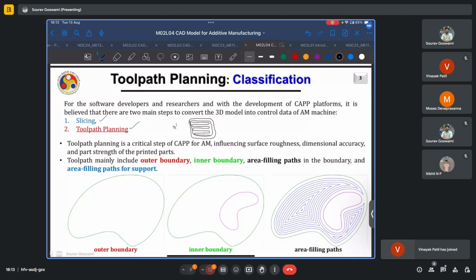And if this is for the nth layer, in the n plus 1th layer, based on the type of variation which you have, if you give any interlayer rotation or not, you will again have something similar. In a sense, it will be 1 or 2 perimeter passes. And then the infill, say if you have an interlayer rotation by 90 degrees, in this case, the zigzag or bilinear filling pattern will resemble something similar to this.